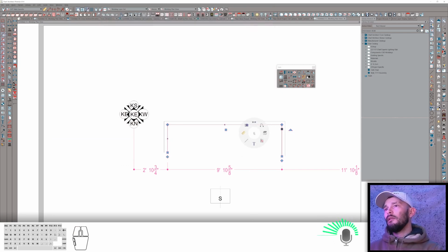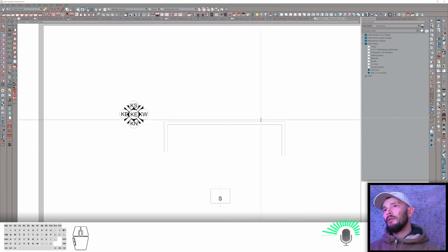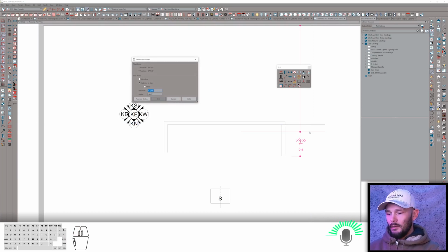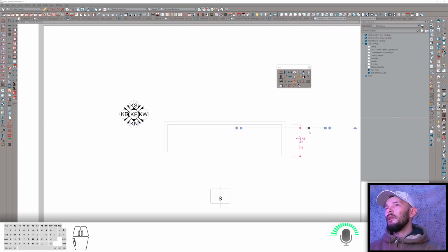Now I'm going to draw a line, and you can see it extruded on the outside of my polyline, okay? So I'm going to draw a line, and then I'm going to take that line, drag it down, tab or enter input, Control V to paste. There we go. So now I'm going to use this to trim. I'm going to trim off this excess down here.